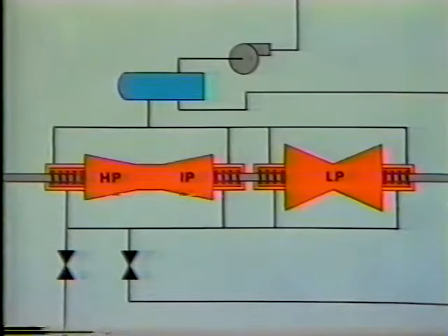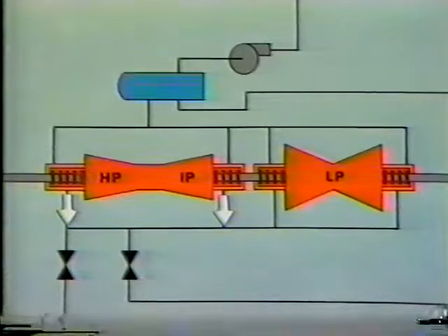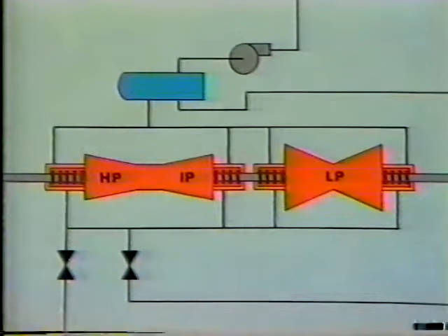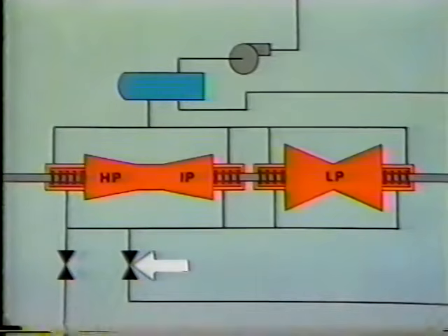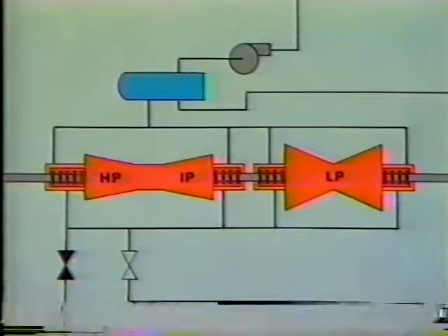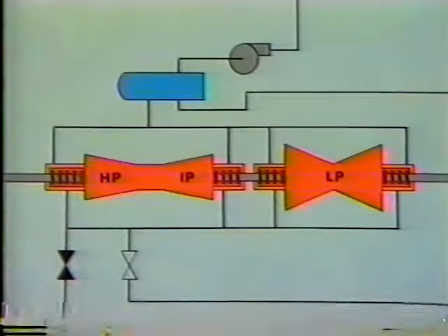As steam pressure inside the turbine continues to increase, more steam is fed to the supply header, increasing the header pressure. To maintain the header pressure at 3 to 5 psi, the steam unloading control valve opens and routes the excess steam to a low-pressure area, such as the main condenser or a low-pressure heater. Maintaining header pressure at 3 to 5 psi keeps the turbine sealed.